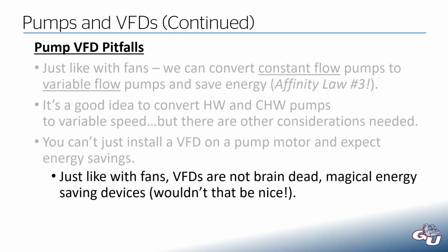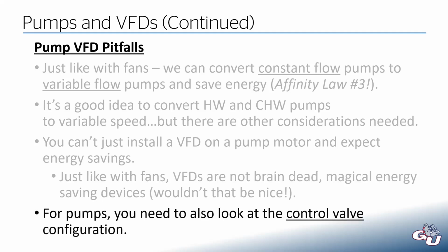Because as I've explained to many maintenance personnel over the years, you can't just slap a VFD on something and then just get energy savings out of it. It's not this magic thing that just saves energy. You have to think about the entire system and what is actually going to cause that VFD to reduce its speed. For pumps specifically, you need to look at the control valve configuration.